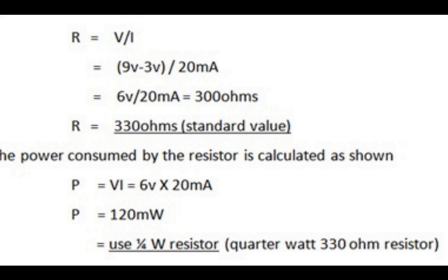See the calculation. Normally, a 5 mm LED draws a maximum of 30 milliamps current and requires 2 volts to power up. Here we are going to design for 20 milliamps current and 1.5 volt per LED. For two LEDs in series, 3 volts is required because voltages in series are additive. So, two LEDs of 1.5 volt each require 3 volts to power up.